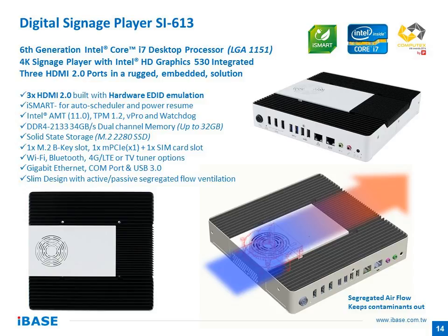It also has EDID emulation built into it, so you don't have to worry about the whole EDID issue. If you disconnect a cable, if a display gets powered off, if somebody broke one of the displays, the digital signage software will know about it, and the other displays will continue as if nothing has happened.